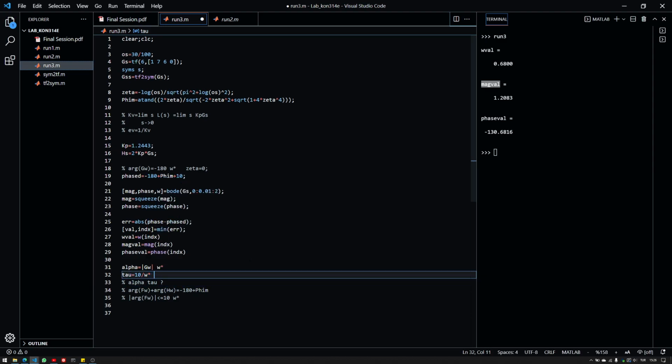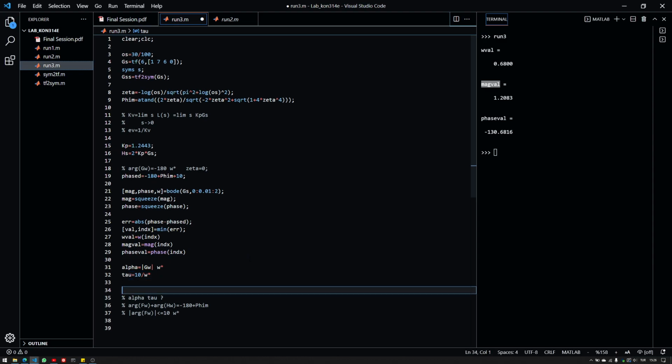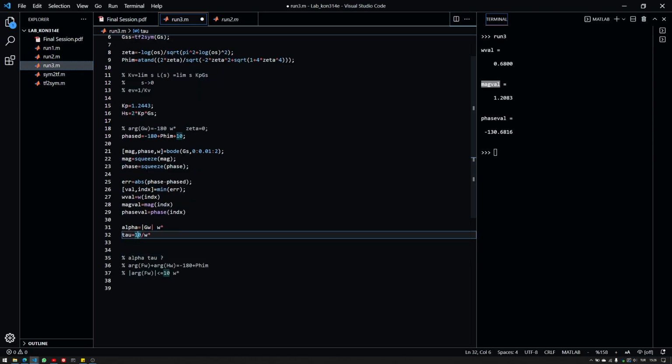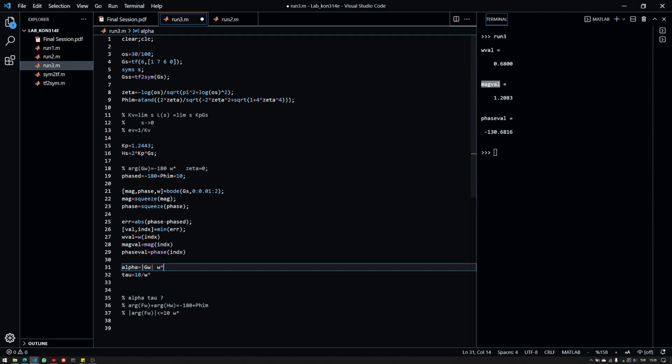This is maximum tau. So these two equations give you the lag controller that you need. And that's basically it. The frequency methods are always the same. You have some theoretical aspect, and you use that aspect, read some values of the phase plot or magnitude plot, and you use these relations and you're good to go.